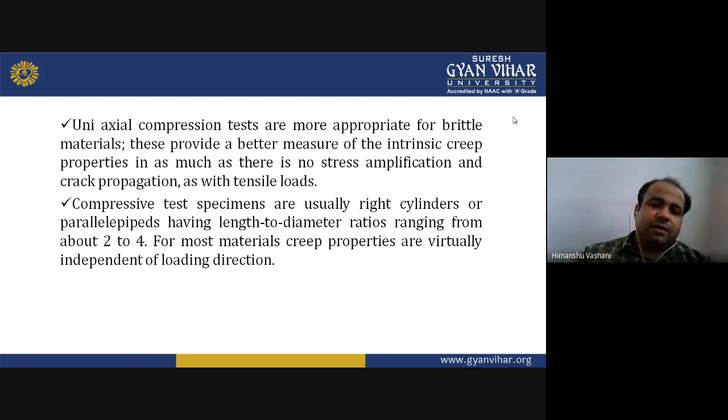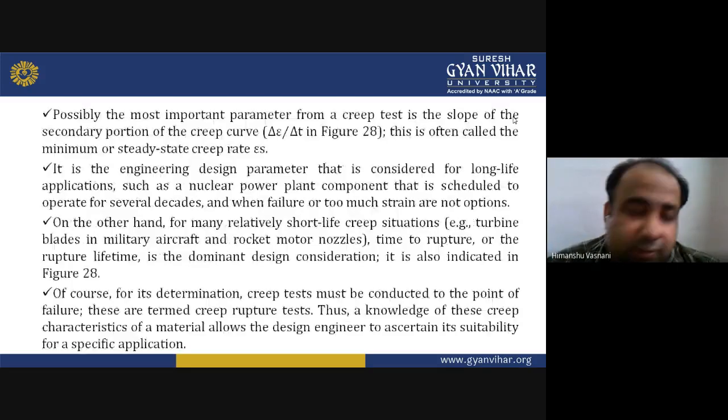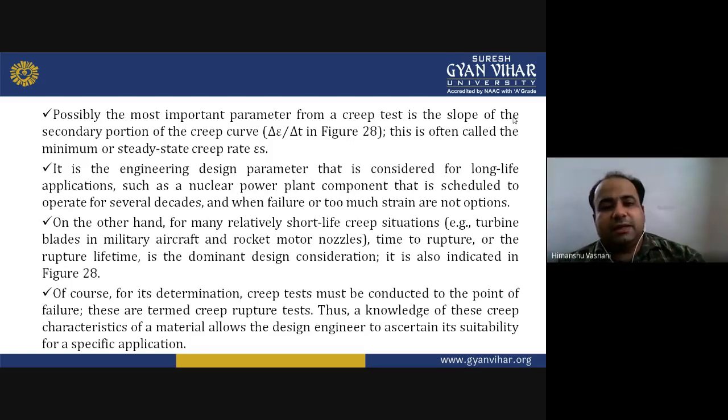So here we understand what importance creep has. Possibly the most important parameter from a creep test is the slope of the secondary portion of the creep curve. The secondary stage is also called the minimum or steady state creep rate. Now it is the engineering design parameter.